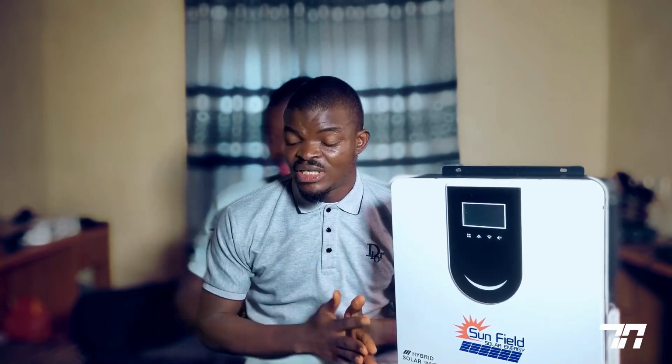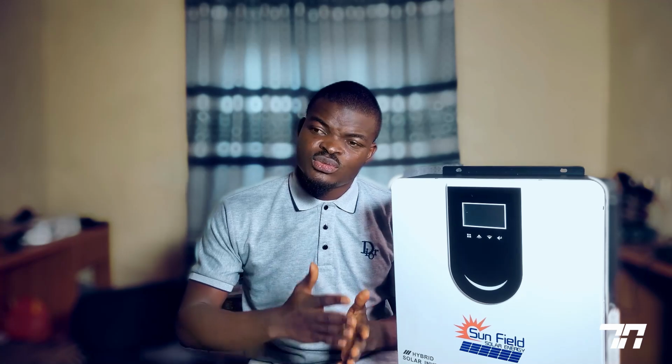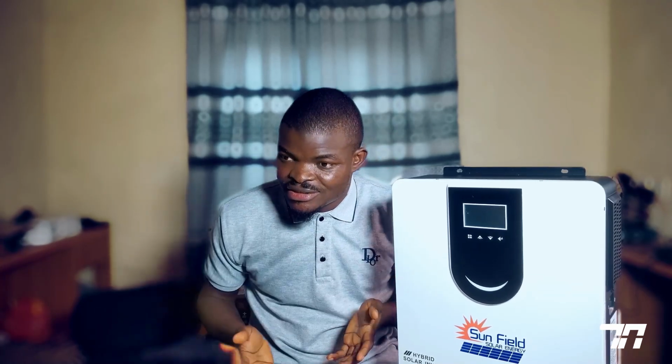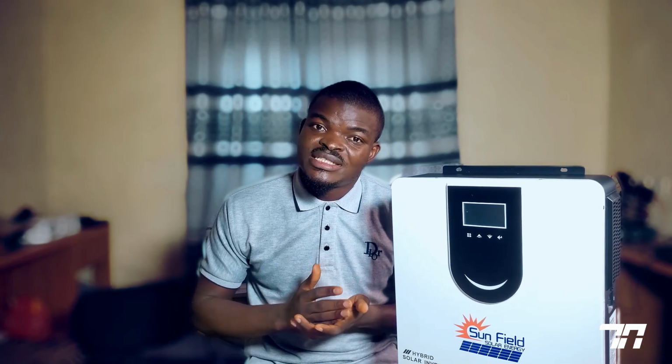In our low frequency inverter, charging frequency, we all know when the frequency of your supply is not within the range of 49 Hz to like 51 Hz. Let's say you are using a generator. Even if your voltage is 220, the inverter will not charge. It will reject it. Let's say your frequency is around 49 to like 51 Hz.